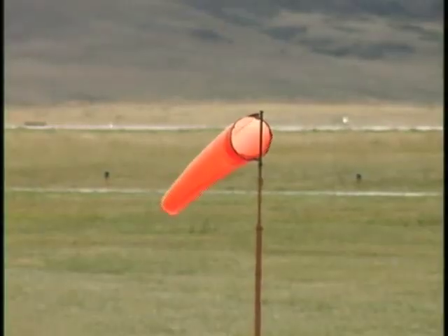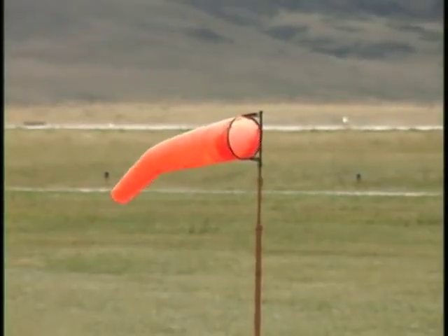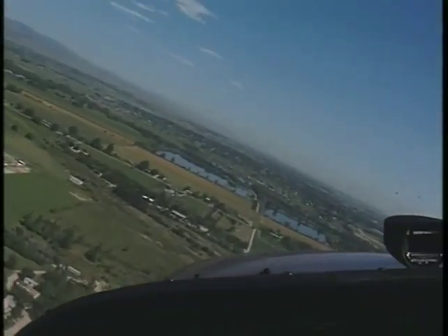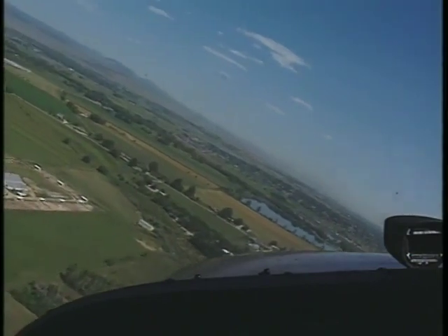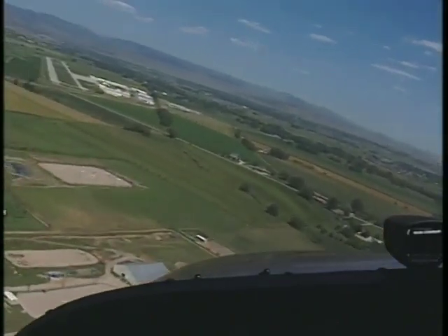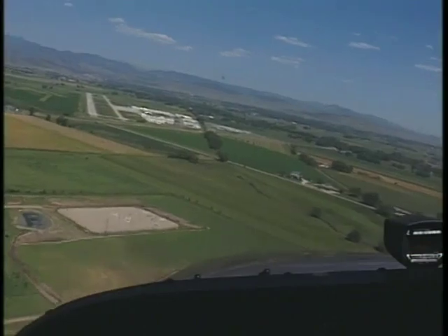Take time to evaluate your aircraft's performance in various wind conditions and with a variety of flap settings. Doing so enhances your ability to judge altitude, glide angle, and distance. If you can accurately estimate your glide angle and its resulting distance, you can judge how much maneuvering is possible to safely reach a given spot on the ground during an emergency landing.